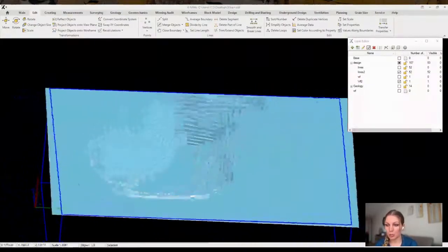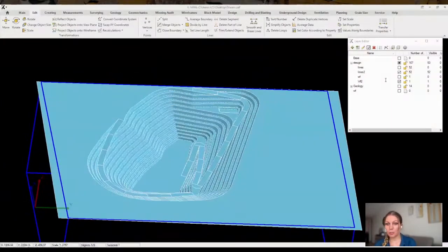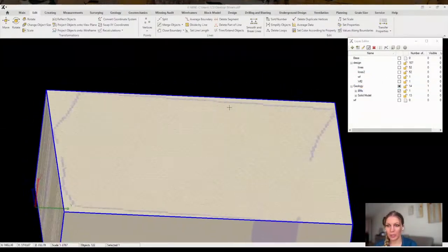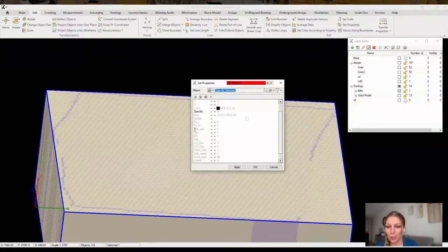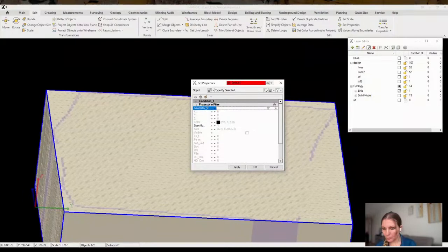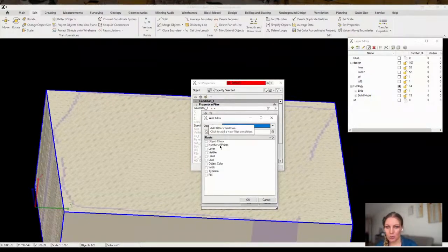So in order to develop a project to search for optimal contours, we require a block model and the current mining position in the pit. However, to consider the present state of mining operations during the optimization process, we must restrict the block model to a wireframe before incorporating it into a project. To achieve this, we utilize the set property command and choose the appropriate geometric constraints.